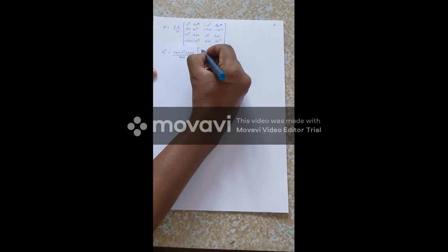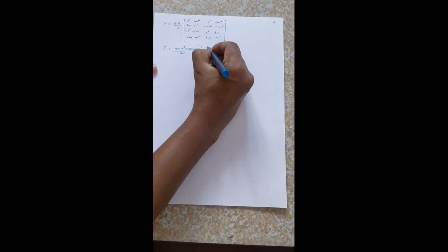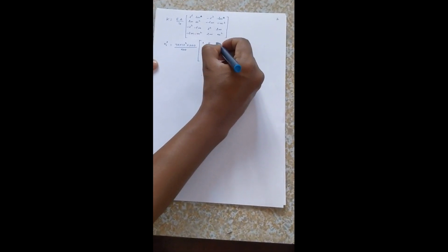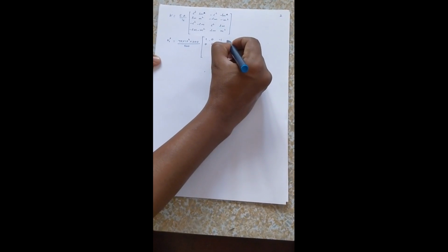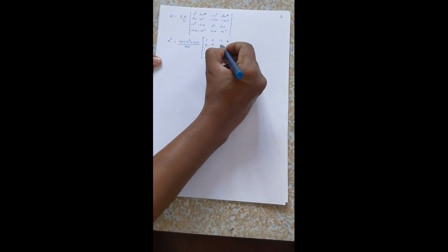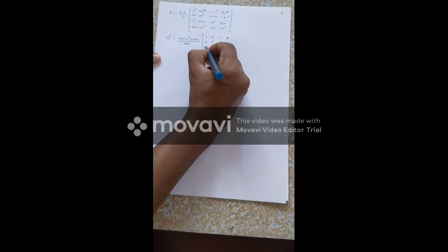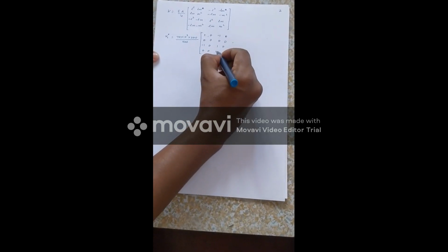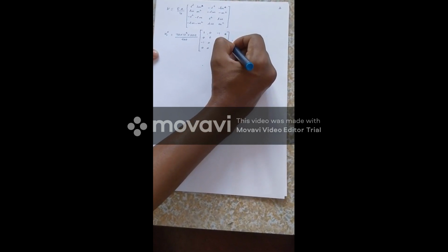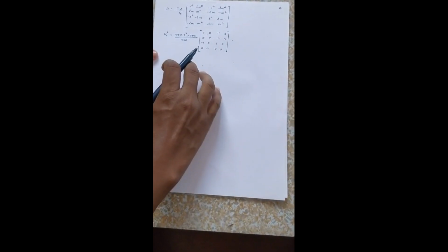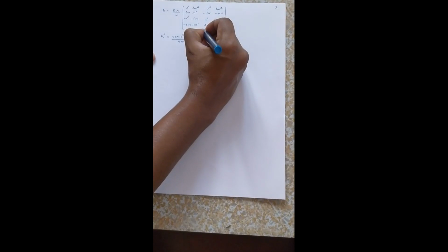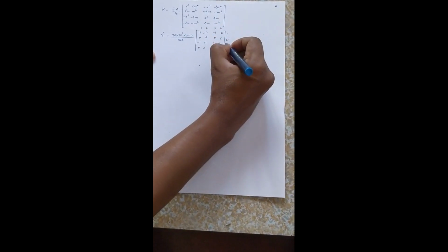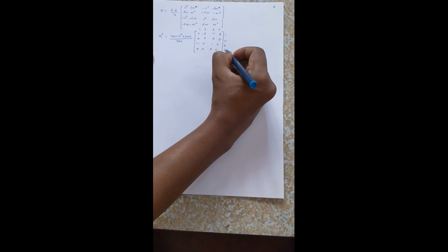L square is 1, LM is 0, M square is 0, so the matrix is 1, 0, minus 1, 0; 0, 0, 0, 0; minus 1, 0, 1, 0; 0, 0, 0, 0. And since element 1 is made up of nodes 1 and 2, its coordinates will be 1, 2, 3, 4, 1, 2, 3, 4.